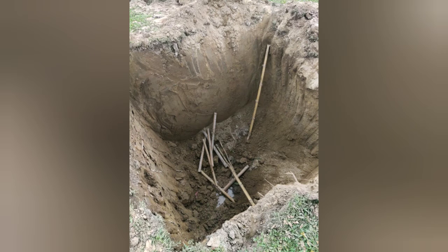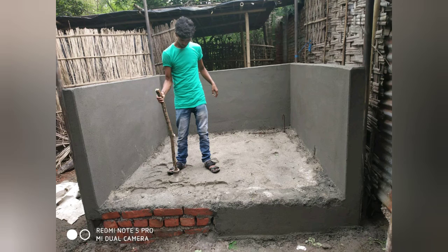In this method, the width of the foundation trench is increased by 300 mm or so, and then a layer of rubble is spread in a thickness of about 300 mm to 400 mm over the bottom of the foundation and rammed. If the rubble gets completely buried into the soil, another layer of rubble about 150 mm to 250 mm is spread and rammed. The foundations treated in this way show considerable improvement in their bearing capacity.